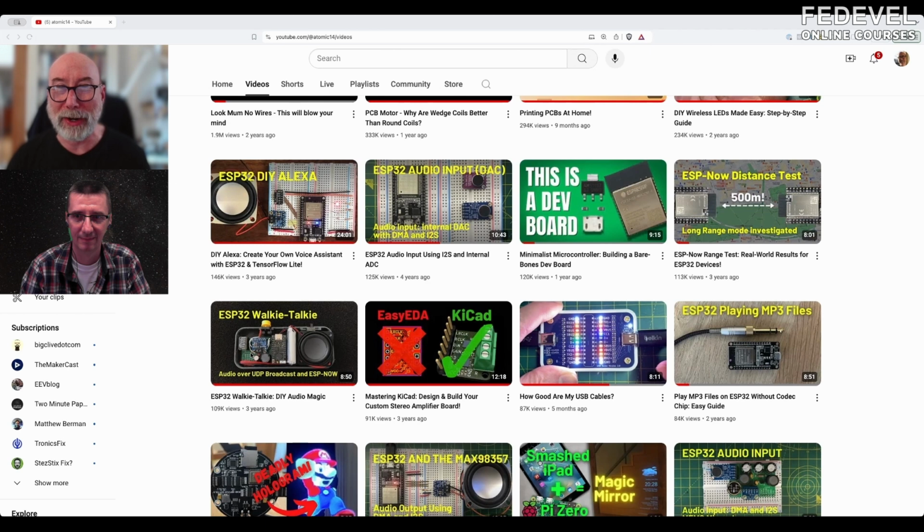And with my vague memories from my degree, and enough looking around at other people's projects and modules and Arduinos, I knew enough to be dangerous in some PCB design software. So it was kind of like, oh, all the headers are 2.54 millimeters, so that's probably a standard thing. I'll just stick some of those in. I need 5 pins, and there's VCC and ground. So I think it was just jumping in and trying it and hoping for the best.